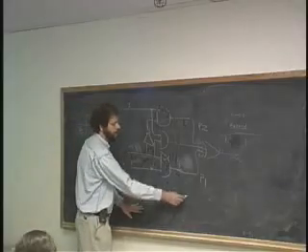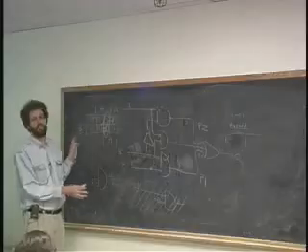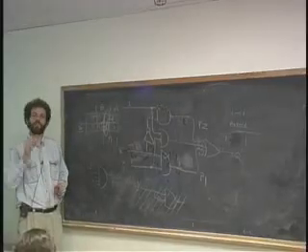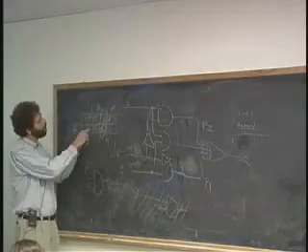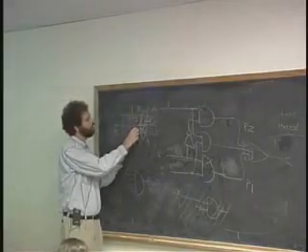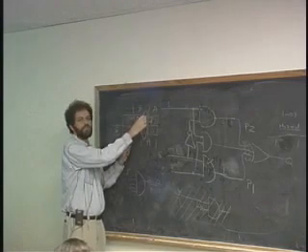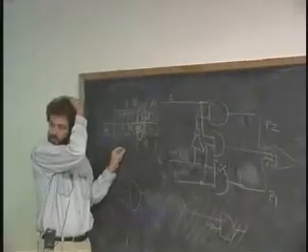So for any practical sum of products logic circuit, you can never get a 0 to 0 hazard. Again, for single input change. And if you cover the path with AND terms so that there's never an interruption of these circles as you transit around, you can never get a 1 to 1 hazard.